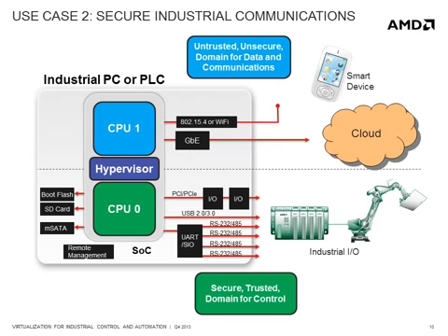By partitioning each virtual machine, virtualization offers complete isolation for each subsystem. Through isolation, each machine is protected from crashes and/or viruses in the other machine. In this example use case, in the event CPU 1 crashes and is unable to transmit data on factory operations to the cloud, the PLC is still able to operate deterministically on the plant floor, thus mitigating the need to shut down the entire machine for maintenance and support, which would result in loss of productivity.